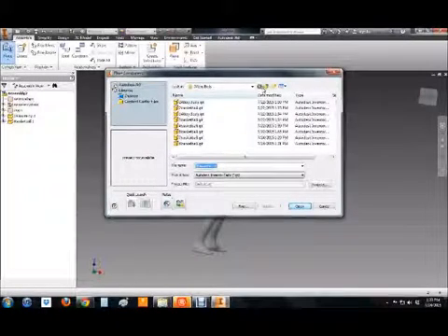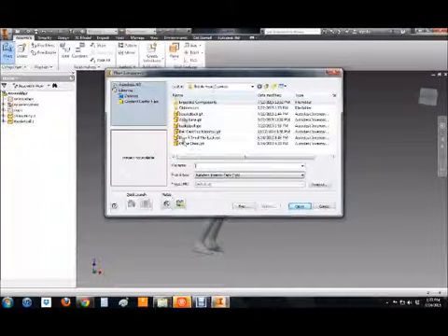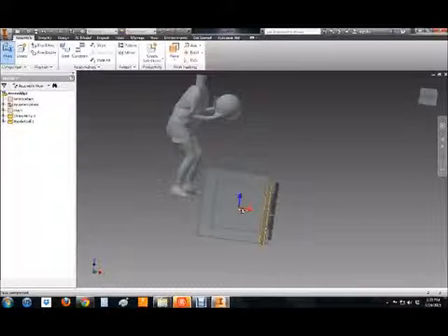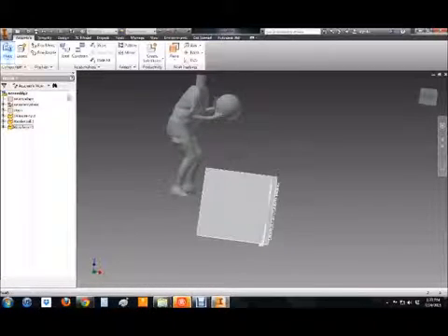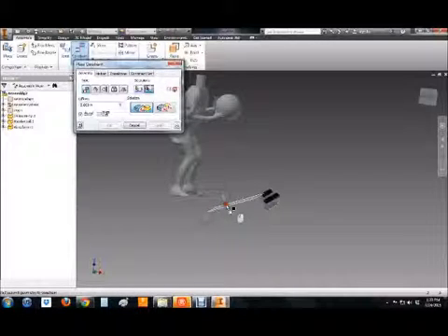I'm going to grab Abby's base that we used to make her. Let's see, so Abby base, we'll bring that in and click that into place. So that's good. And then I'm going to free rotate just this piece and get it in the general orientation of where we want it to be, so it makes it a little easier. Because you'll see when we mate her feet to the base, it's going to go a little also kablooey. So we're going to go to Constrain and choose Mate, which is the default choice there.